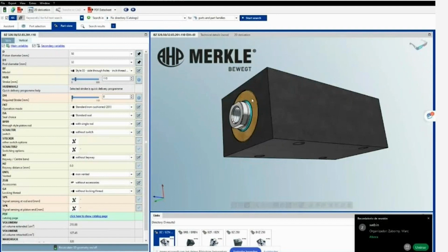Hey, Ricardo. Yeah, because also the additional work that there is in plumbing. If you choose a block cylinder, you have external plumbing, you have to do it at the same time. But I can say in Europe, it's very common to see the plumbing being done in the mold base itself. So it's easier to assemble, it doesn't occupy so much space, and it doesn't tend to break the connectors, and it's cleaner, let's say.